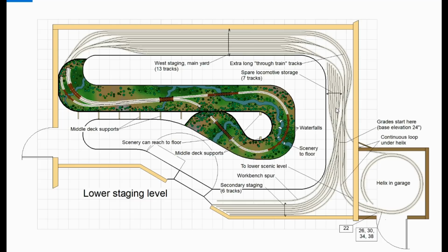Around the walls, the benchwork sections are a maximum of 32 inches deep, and that can easily be handled on heavy-duty shelving brackets, such as the ones that I used on my own layout. The vertical tracks can just be screwed directly into every other stud, giving you a nominal 32-inch spacing, and with the long 22-inch brackets, that will give you plenty of strength.